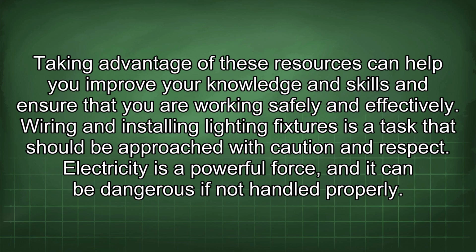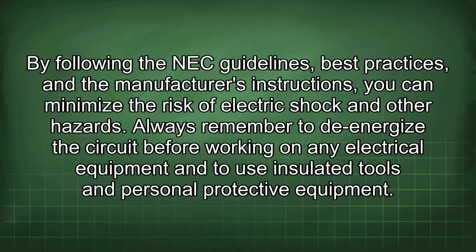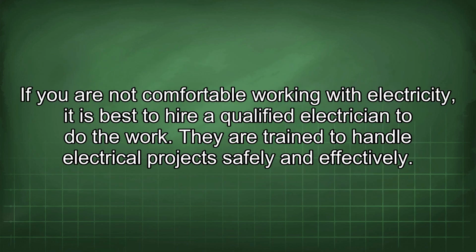and effectively. Wiring and installing lighting fixtures is a task that should be approached with caution and respect. Electricity is a powerful force, and it can be dangerous if not handled properly. By following the NEC guidelines, best practices, and the manufacturer's instructions, you can minimize the risk of electric shock and other hazards. Always remember to de-energize the circuit before working on any electrical equipment and to use insulated tools and personal protective equipment. If you are not comfortable working with electricity, it is best to hire a qualified electrician to do the work. They are trained to handle electrical projects safely and effectively.